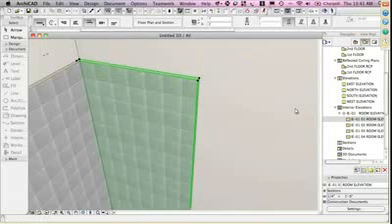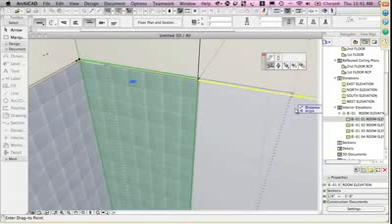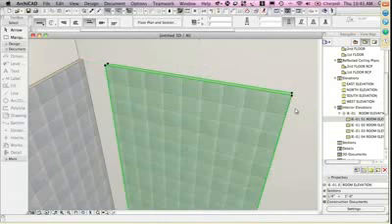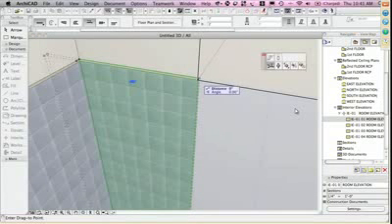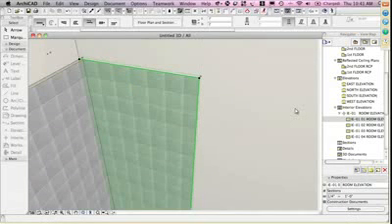So I'll take this wall. I'm going to press down here and say I'd like to drag it. Now, if I drag it sideways, press the Shift key, I've just moved it sideways. I'll undo that. Instead, I'm going to press and drag it and move it on top from one corner to the other. So now it's basically being buried into the wall. So you can see how it's now flush in the wall. Now, this can work, but it could get to be a problem because the two walls are essentially overlapping each other. So in other words, both surfaces are competing in the 3D world.